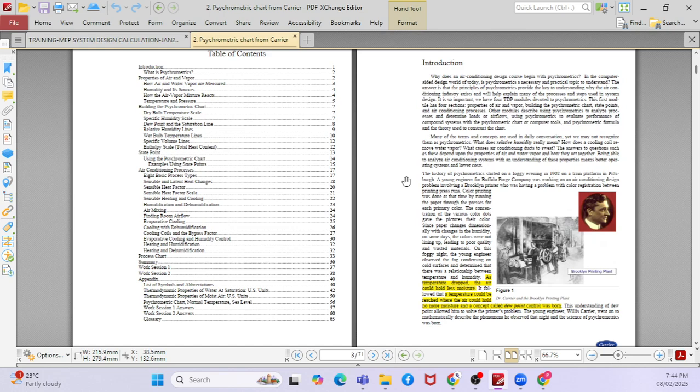Okay, see, basically, I will tell you that not all spaces are uniform. Say for example, when you go to the kitchen spaces, you have a different temperature. When you go to the residential, you have a different temperature. So these are the different spaces. Even for a residential project, we will be referring to ASHRAE, but the actual will be based on your actual calculations, right?